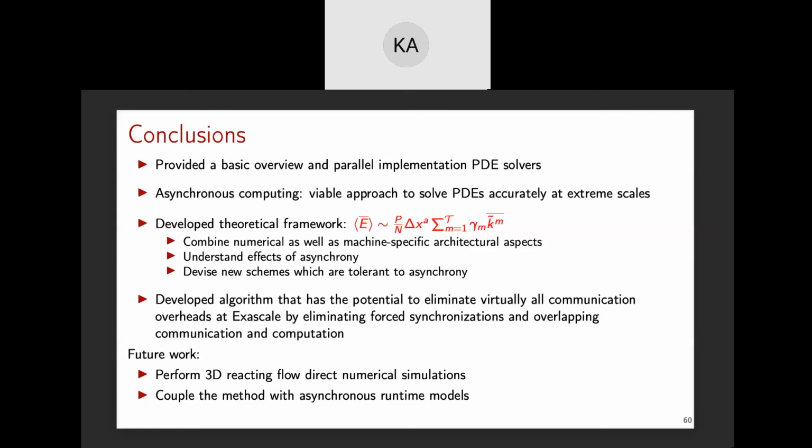So what we have done, I will tell you in the context of reacting flows, is that we did not directly implement all of this in a 3D code, which would obviously take a lot of development time, and we do not know whether it will work or not. So there are high risks as well. What we have done is we have implemented this in a simple 1D code, a 1D reacting flow. Overall, the nature of chemistry that you would encounter would remain the same, but the flow is 1D. We have extensively developed benchmarks based on standard problems that are used to validate premixed flame, auto-ignition, non-premixed flame, and detonation. So we have validated with all of these. In the paper that is under review, we have considered around 7 cases of different types of combustion events, and validated all of them, both in physical space as well as spectral space.